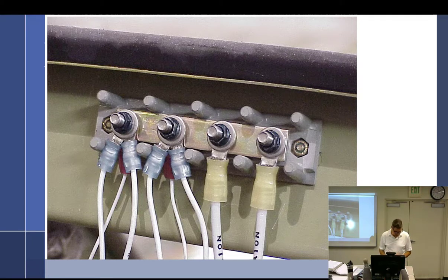All right, use the proper crimping technique. Technically, crimpers are supposed to be calibrated. And the nice thing about, you saw that one, it put a double crimp. So it crimps one on the shielding. So when you're pulling the wire, it's actually grabbing the shielding and the wire. And avionics guys, the good ones, they will crimp, they will solder, and then they'll put heat shrink over the top of it. They never use just strictly mechanical. I do, but let me see.